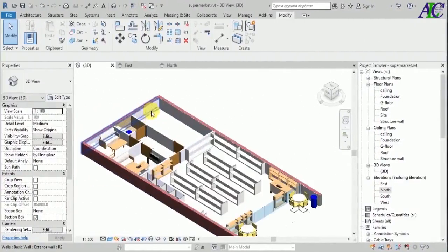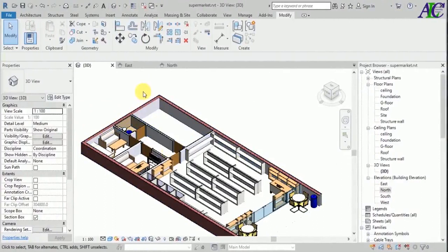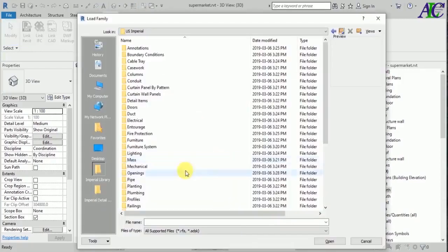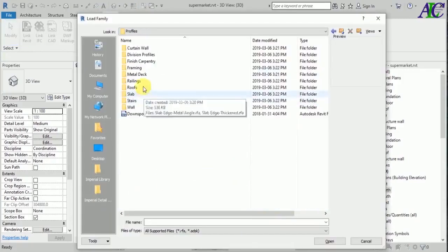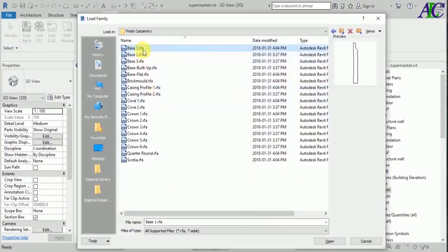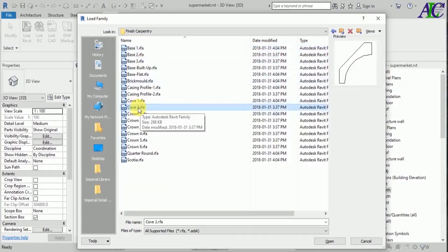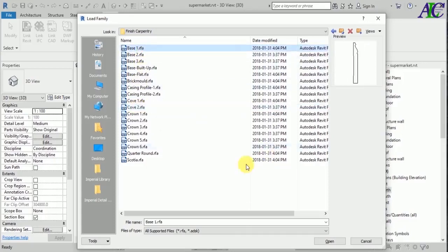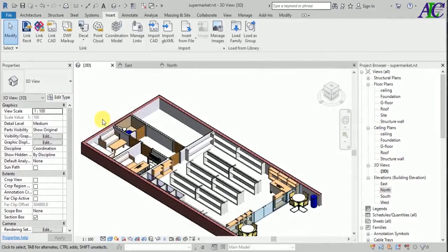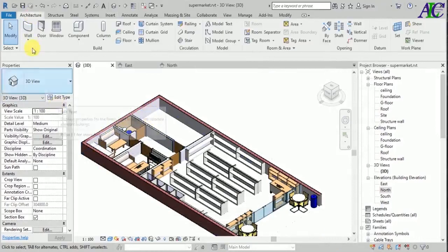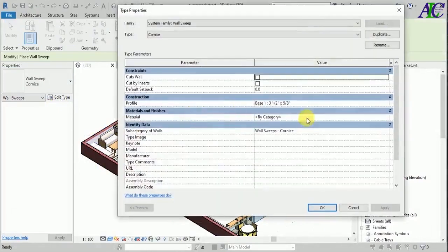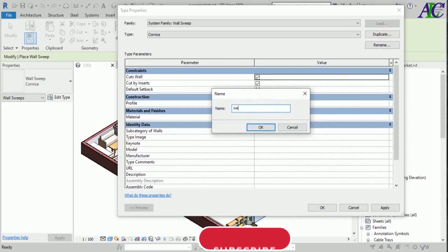So now I'm going to create the wall shape, and then let's lay profile, finish perpendicular, and then let's select this one, maybe base one. Okay, so let's go to architecture and then wall. So let's duplicate this wall shape. Okay, maybe wall shape 1,